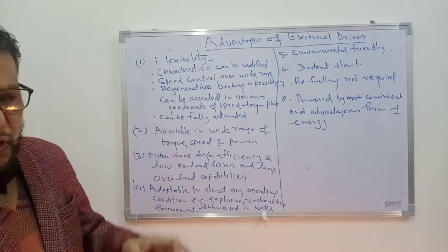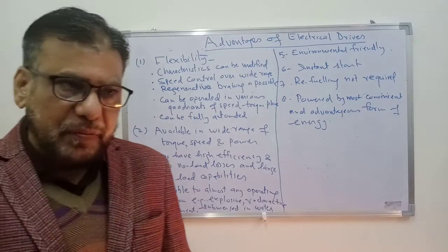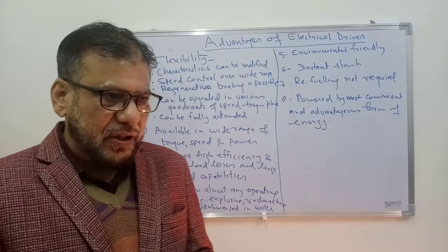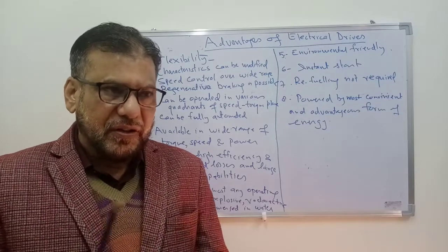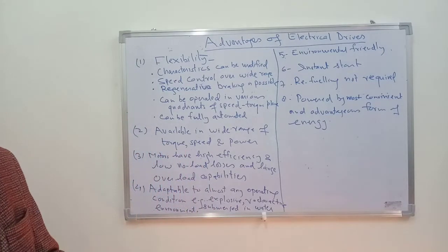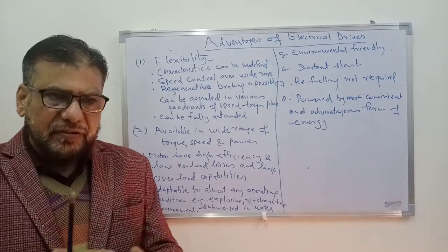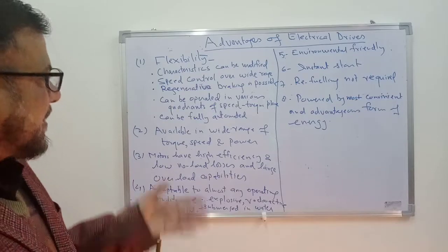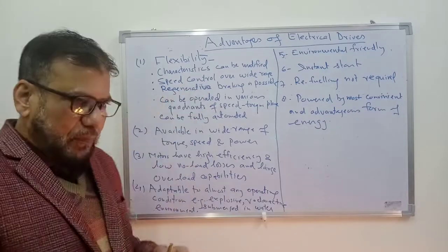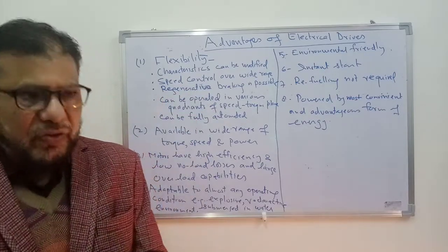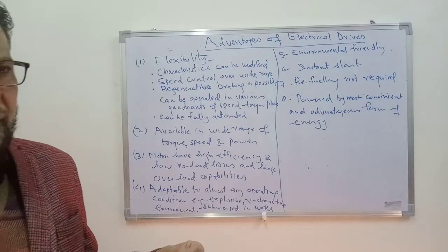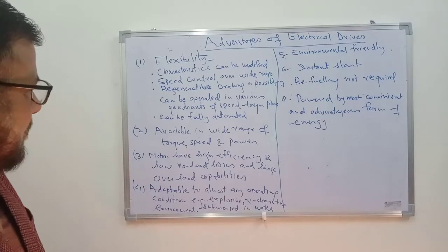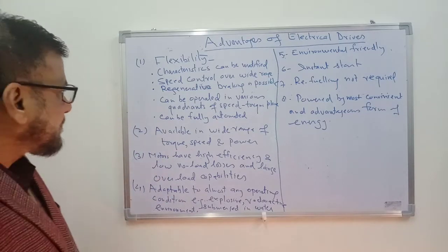It can be used for regenerative braking also. That is when we have to stop the motor, stop the drive or reduce the speed. So during that period, energy stored in the mechanical system of the drive can be fed back to the source. That is known as regenerative braking. So that energy is not lost, it can be recovered and can be sent back to the source. So this is also possible in electrical drives.